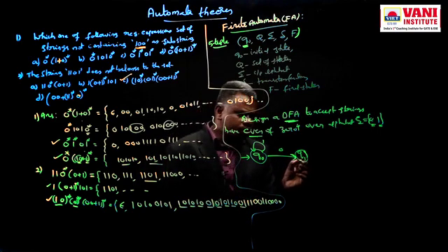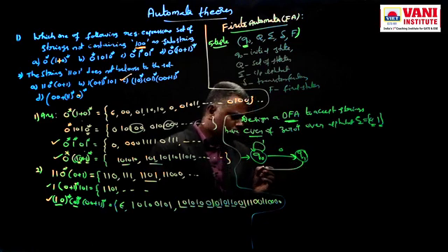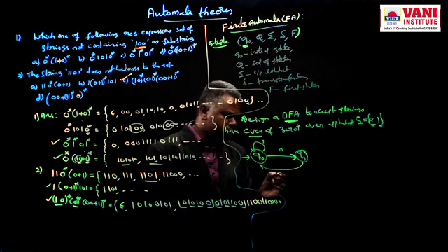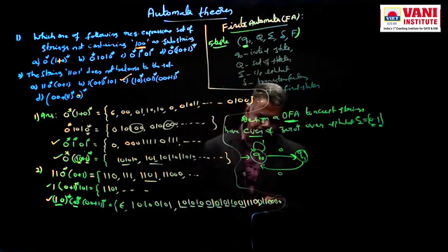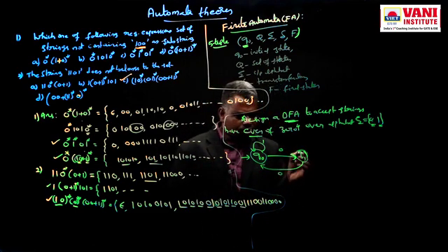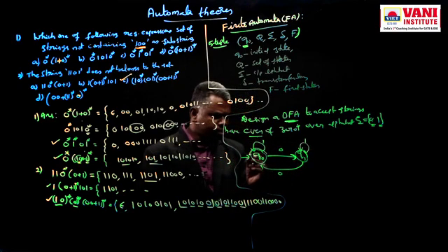Suppose in this second state it sees one more 0, let it come back to the same state Q0. Let us exercise this, and if not, we can modify the diagram. In this state, on a 1, let it stay in the same state. I am marking the initial state as the final state too.